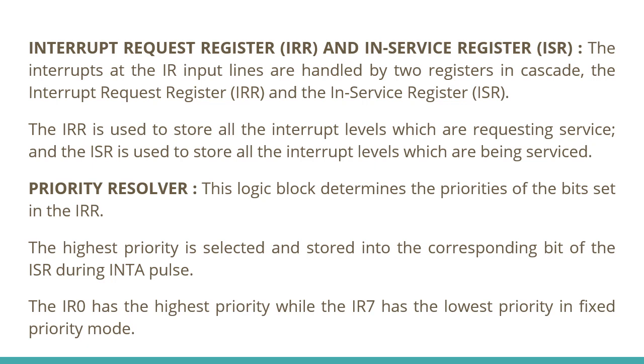The IRR stores all the interrupt requests in order to serve them one by one on the priority basis. The in-service register stores all the interrupt requests that are currently being served. That is, the ISR keeps a track of the requests being served.